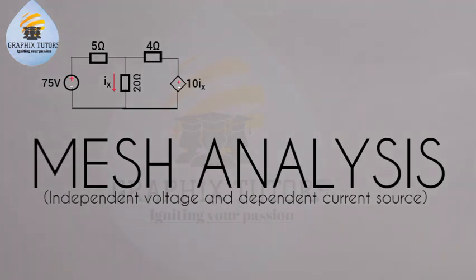So if you look at this circuit closely, you discover that we have 3 passive elements and 2 active elements. The 3 passive elements are the resistor of 5 ohms, the resistor of 20 ohms, and the resistor of 4 ohms. And 2 active elements, which are the independent voltage source, 75 volts, and the dependent voltage source, which is given as 10Ix.